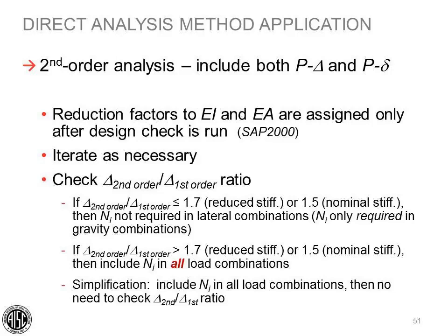Okay, and then in the first order and the second order drift models, do you still need to apply the notional loads? In the first order and second order drift, when we're checking, I assume the question is pertaining to checking drift for wind drifts and seismic drifts, as opposed to whether or not we need to include the notional loads, or whether or not we can use the effective length method. In those cases, you would not need to include the notional load to check the wind drift or to check the seismic drift.